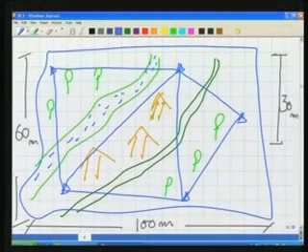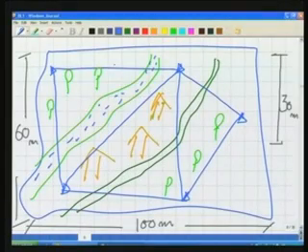Now, what is the meaning of that? Once you have gone into the ground, you can do these measurements easily, isn't it? You have got the tape, you spread the tape and measure these distances. The only thing is keep your tape horizontal, because we consider our earth to be a small flat area. So, by keeping the tape horizontal between these 2 points, I can measure all these distances L1, L2, L3 and similarly. So, all these measurements are known to you.